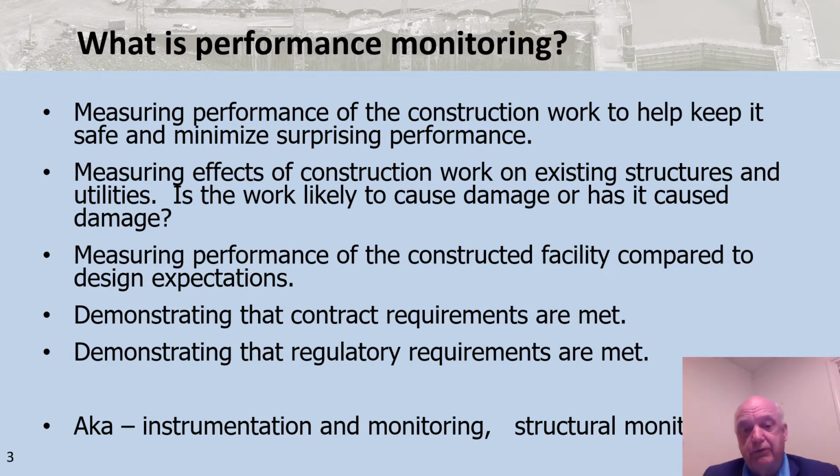Performance monitoring is also known as instrumentation monitoring. So the specifications may have a section titled instrumentation and monitoring. And in many ways, it can also be looked at as structural monitoring, because much of the performance monitoring we do is of a structure. It's of the existing buildings and utilities, or it's of the new works that are being built, or it's of the soil itself that makes up a foundation, and we look at soil as a structure.